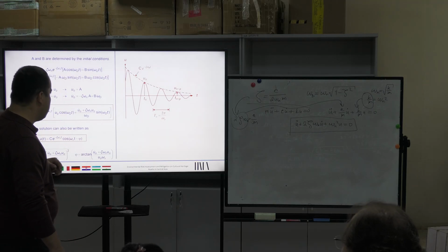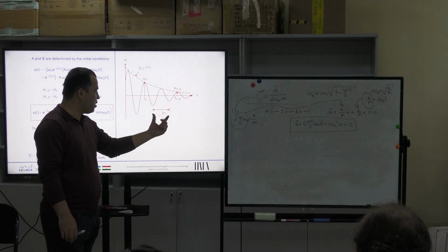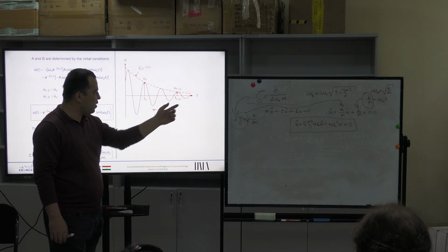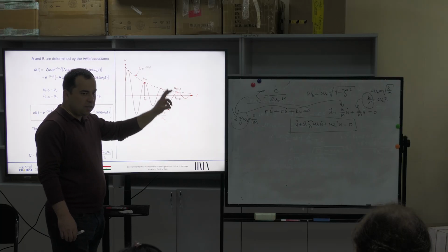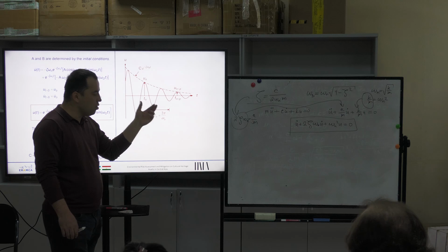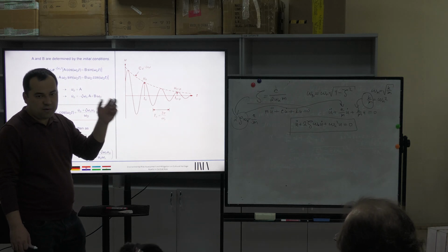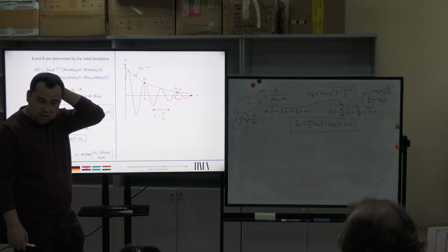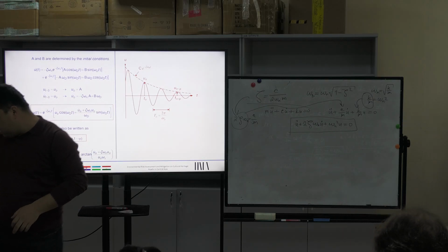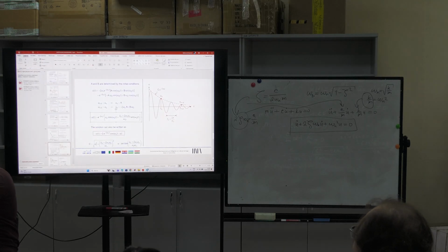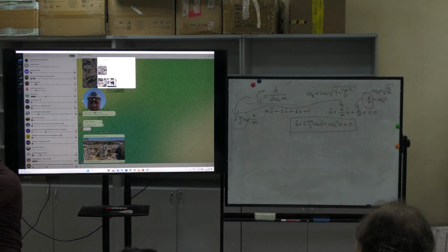And if you look, the period, there is no change. Almost everything is the same. Time, period, frequency is not changing, but the amplitude is just becoming smaller, smaller, smaller. Frequency does not change during this type of experiment. Such a condition is also possible to meet sometimes. When I tested a building, I met the same condition, and now I will show you.